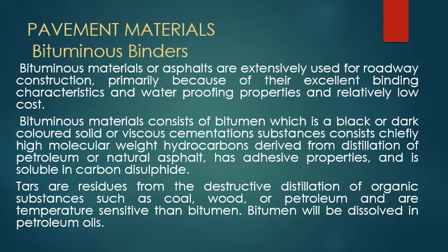But presently, in asphalt mixing plants, proper monitoring is done, and the mix is brought to site at the required temperature, and then laid. During compaction also, we need to maintain a certain temperature to have good quality flexible pavement. And because of this melting and hardening, it is useful for both climatic conditions.